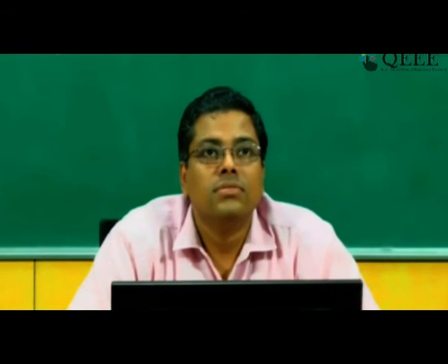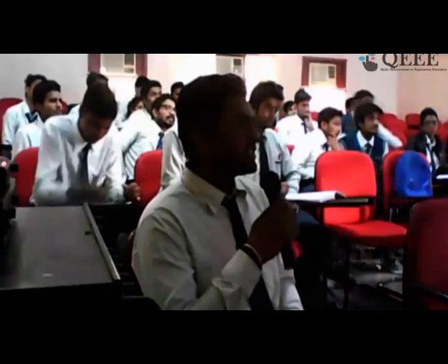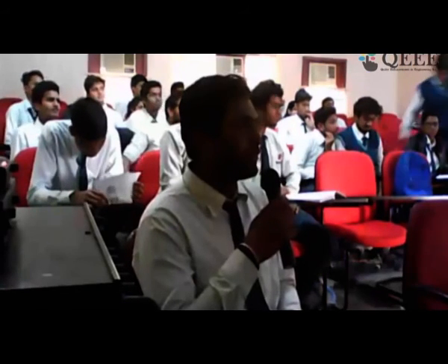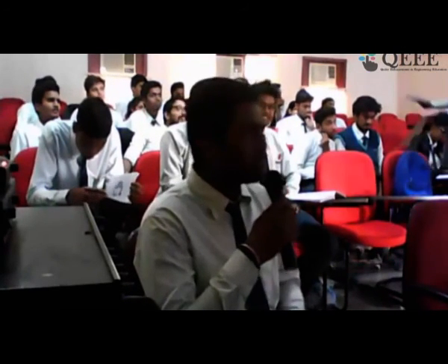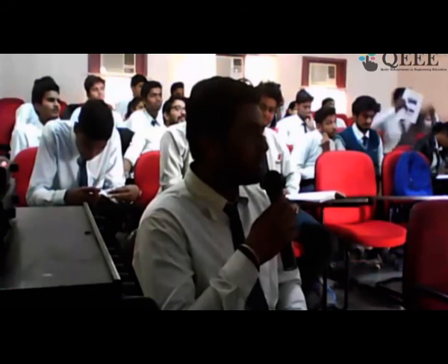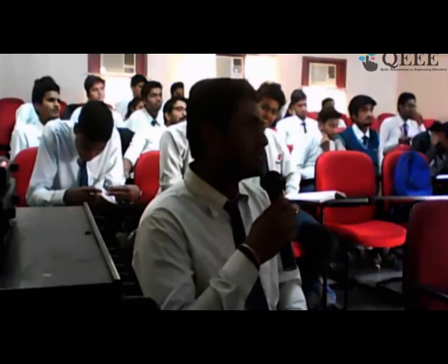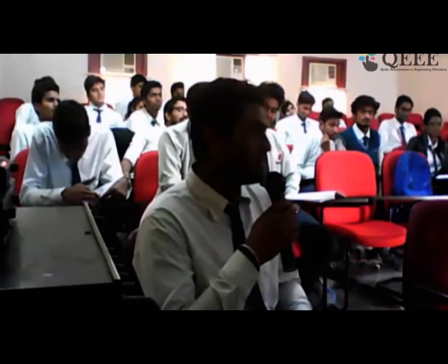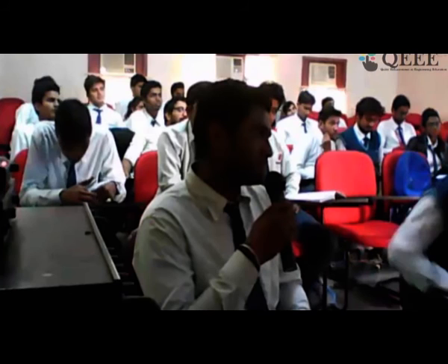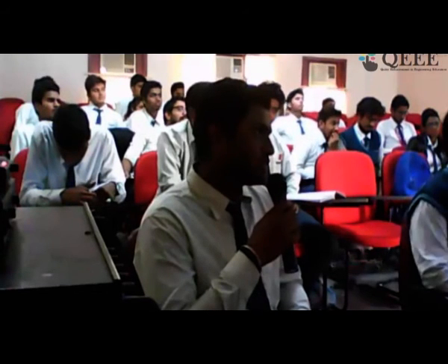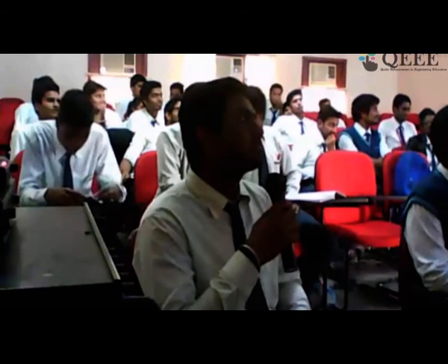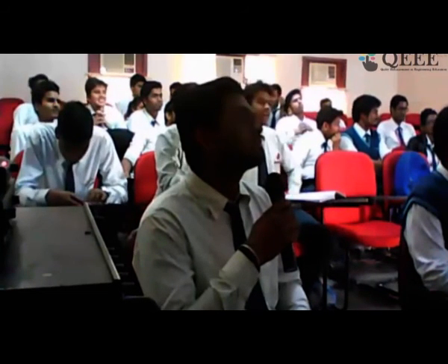Hello. Yes, go ahead. Sir, how is the curing for the precast member different from the normal member of the concrete? It's not different. Then, sir, how can we differentiate between them? Between them means what and what? There is no difference. You should do the same type of concrete, same type of curing for precast members also.